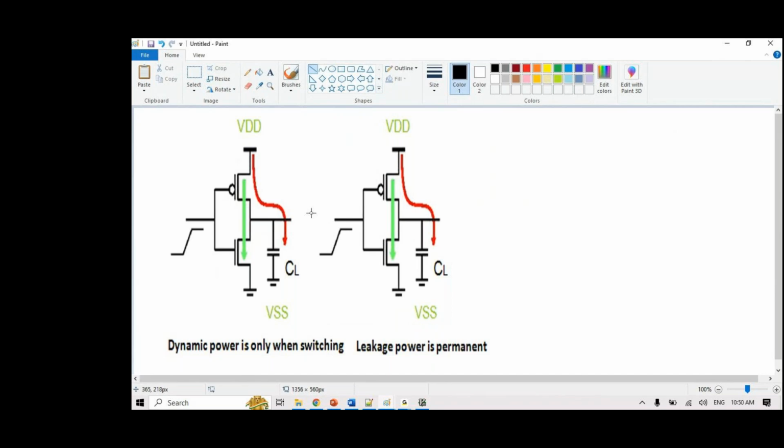There is a connection between this one, right? I'm just taking this to show you. It won't be that an inverter is connected to an inverter. Basically, one logic gate is driving the other logic gate. That's how you can think of it. The output of this will be driving another logic gate, and all of them are driven by the same VDD. This is the same VDD we are talking about. Now, if this transistor is a low VT transistor, what happens as you charge this one? This is a ground voltage, right? You know that this is the ground.